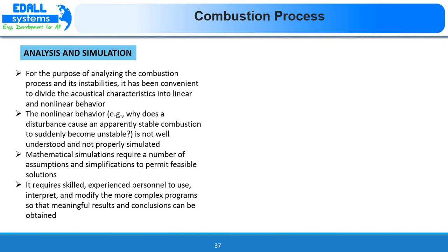So to analyze the combustion process and to understand it very well, the acoustical characteristics have been classified into linear and non-linear behavior. A number of computer simulations with linear analysis have been developed over the last 45 years and have been used to understand the combustion process with liquid propellant combustion devices and to predict combustion oscillation frequencies.